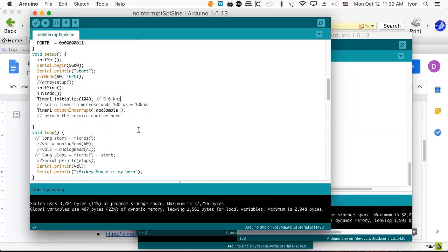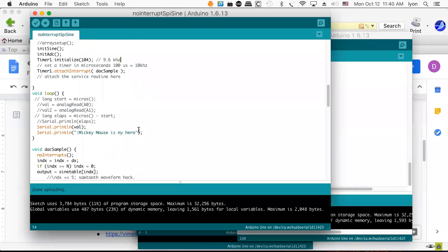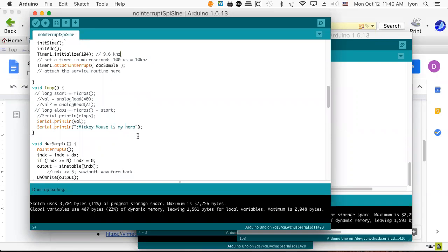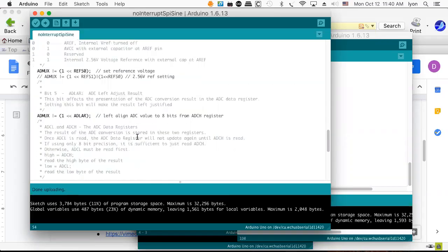And what does that sound like? Just out of curiosity. That's cool. So if instead of digitizing a slowly moving waveform, we wanted to digitize something that was relatively quick, like an analog input, this would be a way to do it, even though the A to D converter is free running, because at least the inputs and outputs would be roughly equal in rate, if not synchronized. So that's the code. What do you think of that?